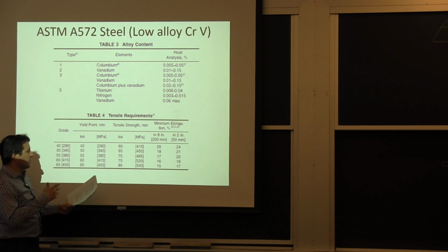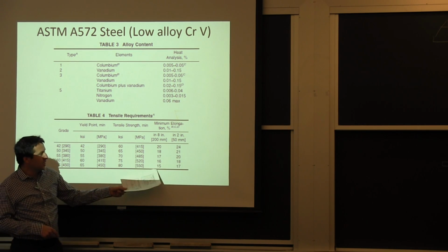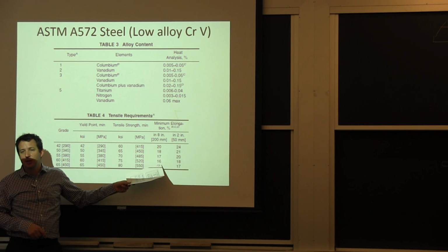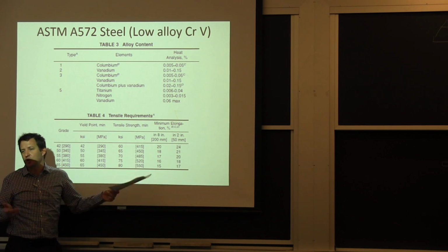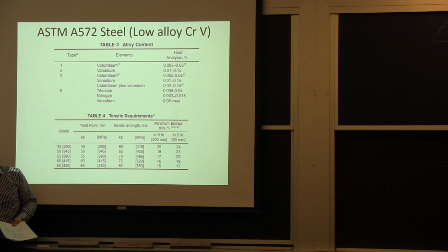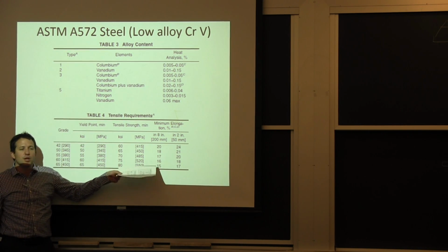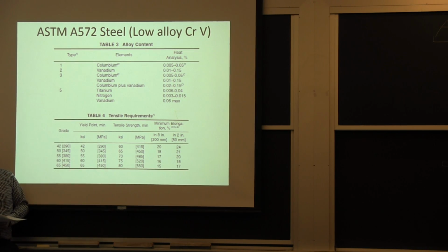One of the reasons for not putting a maximum at this point is that if you want to get these minimum elongations with this chemistry, you can't go too high in terms of cold drawing and cold working the material. Your material can't be fully cold worked, because otherwise you won't have enough strain hardening to get this elongation and break.